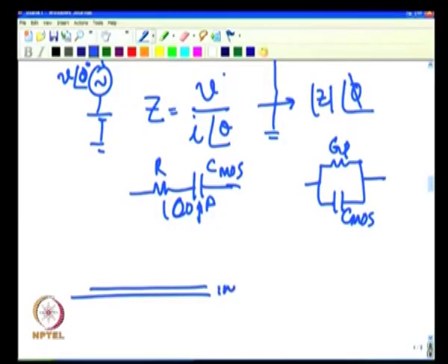If you have an ultra thin gate oxide, then the gate oxide will also leak because of the direct tunneling current that we talked about. If you have a thick gate oxide, there is absolutely no leakage through that. But if you have an ultra thin gate oxide, let us say 1 nanometer, and you have built this MOS capacitor, there is always a leakage here, there is a DC path, and this essentially shows the DC path.